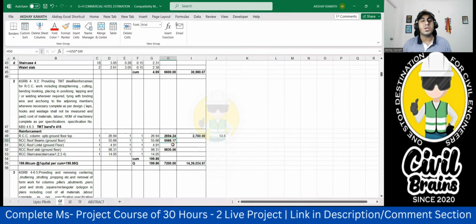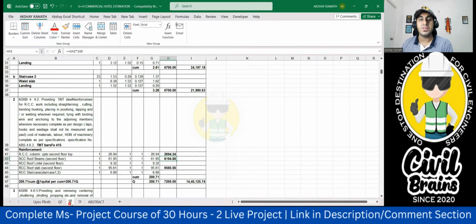Okay, what you do is you take the higher amount only. One thing you need to understand. See, ground floor it was a lower quantity, 5500, but in second floor it was 6500. That means actually here the duration will increase. But not an issue. We'll go with the same duration, 1 or 2 days, nothing. Anyhow, we have taken 2 days extra for all the activity. It will take care of that. If you feel like, no, sir, this is 1000 kg extra, you can increase the duration here. But usually, we'll not do like that.